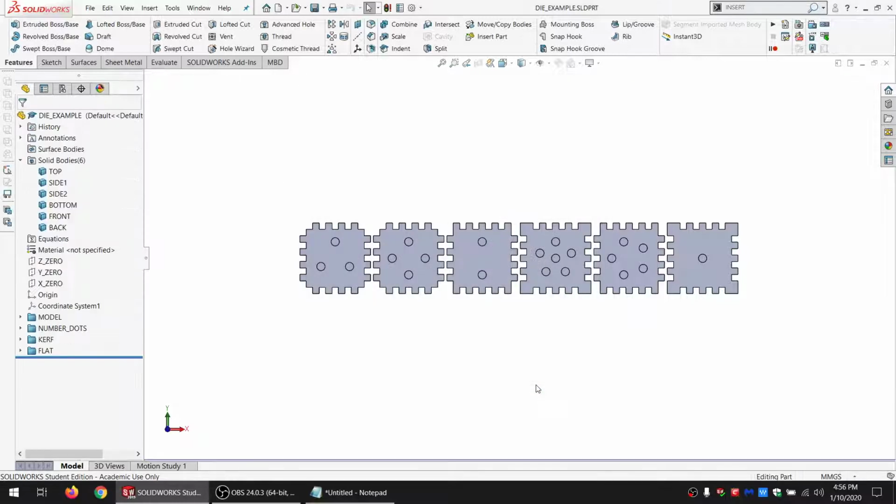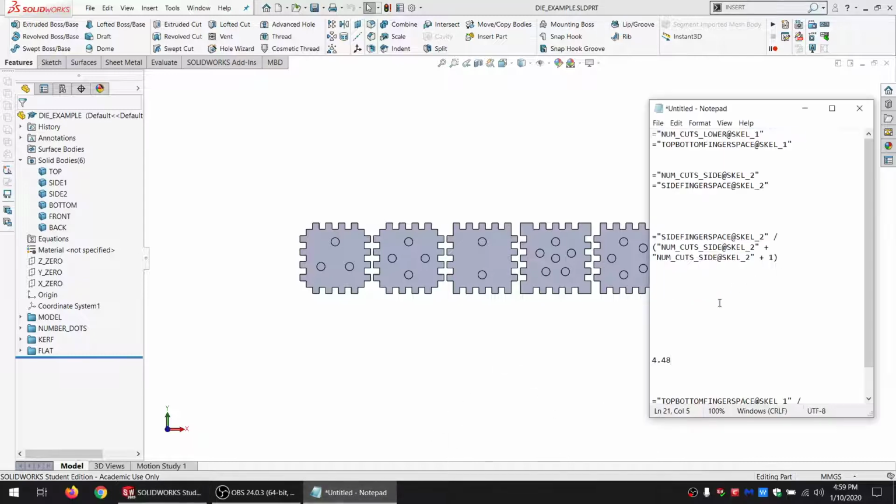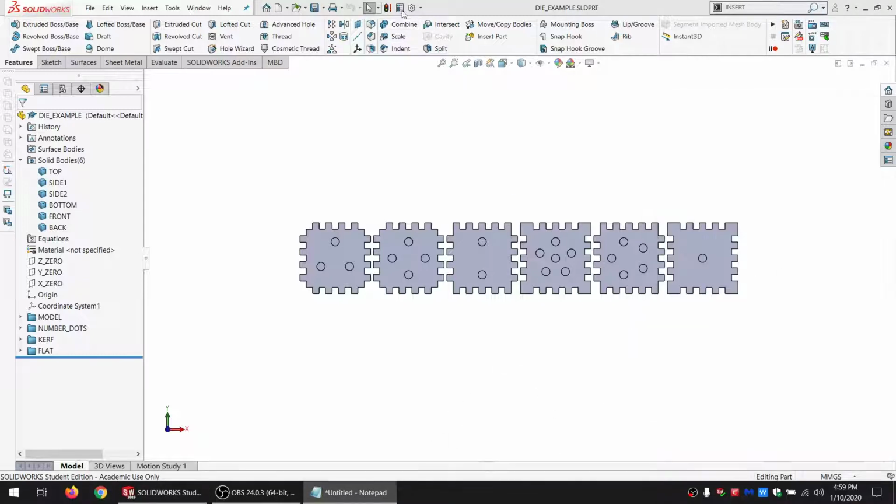We click save, and then we can load it up in our laser cutter software. I'm going to be using a piece of scrap left over from something else I cut, and measured its thickness. Measured at all four corners, and it's kind of long, so I measured about equally between two of the corners on each side to get maximum thickness of 4.48 millimeters.